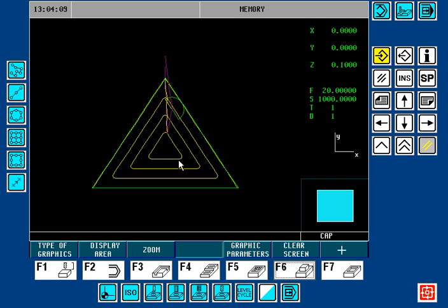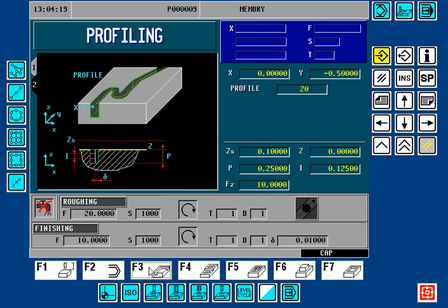So you're not going to have the nested corner start and end feature as part of a pocket. It would only be as part of a profile. And again, because the CNC sees all pockets as closed shapes, but profiles can be open, there's many more considerations to take into effect. Let's quickly recap the nested corner start end, which is exclusive to the F3 profile key.